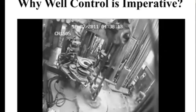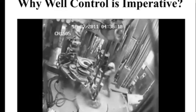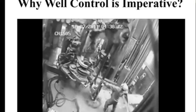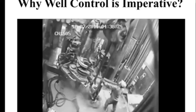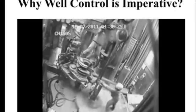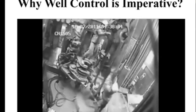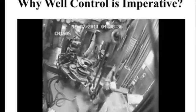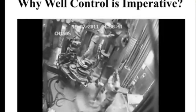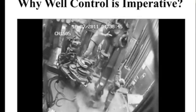Obviously, the reason is something is pushing the drilling mud out of the wellbore. And what we have inside the wellbore to push the drilling mud out is nothing but formation fluid. So obviously, formation fluid is entering the wellbore and the kick is happening. But as you can see here, the crew are not well prepared to deal with the condition.